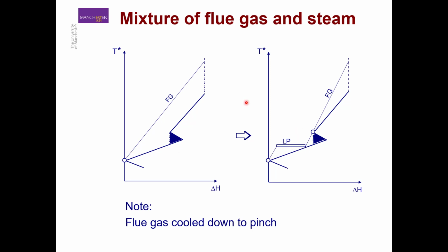In our first process, we are using the flue gas to supply the heating requirement of the process, and based on the supply temperature of the hot oil and the pinch temperature, we can calculate the mass flow rate of the flue gas we need to supply.